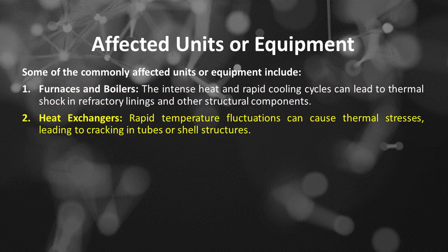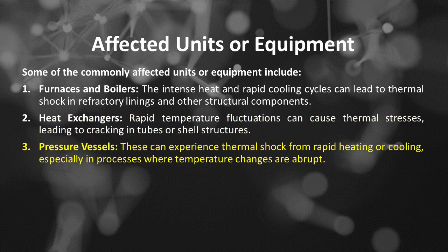Number 2 is heat exchangers. Rapid temperature fluctuations can cause thermal stresses, leading to cracking in tubes or shell structures. Number 3 is pressure vessels. These can experience thermal shock from rapid heating or cooling, especially in processes where temperature changes are abrupt.